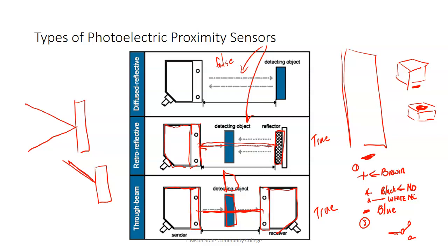With some of the sensors, the wires actually go into the sensor, which means you'd probably have a terminal board out there, but you would have to pull the wire all the way out to the terminal board. Those are cheaper, but if you're using wire ties or something like that, you'd have to cut them off and put them back in there. But most of them would run through like a plastic cable trough.